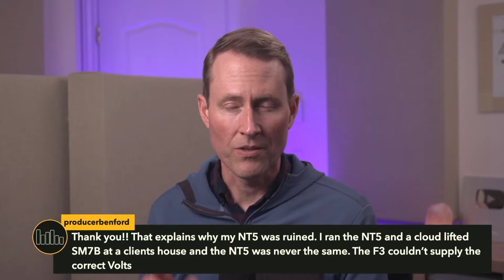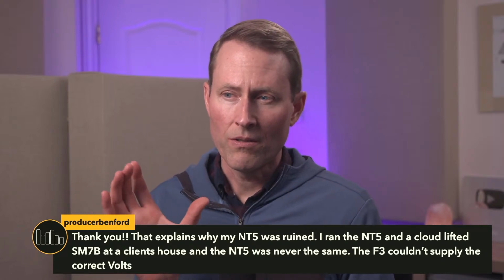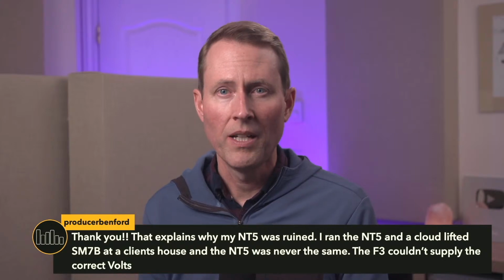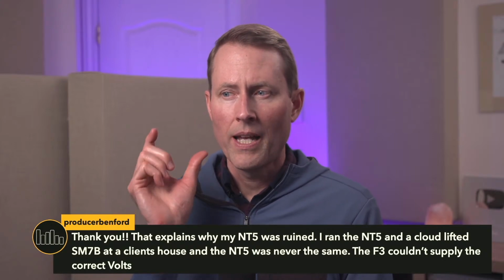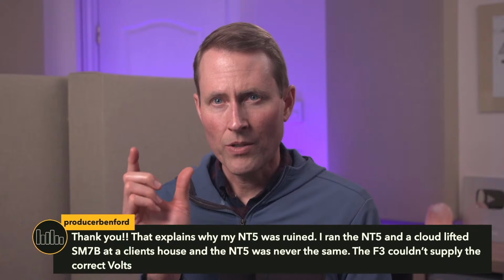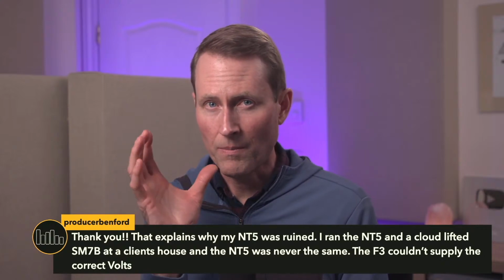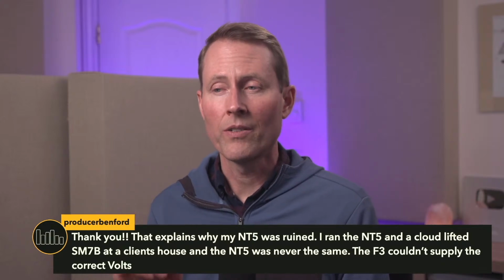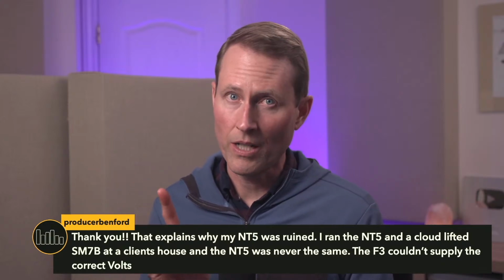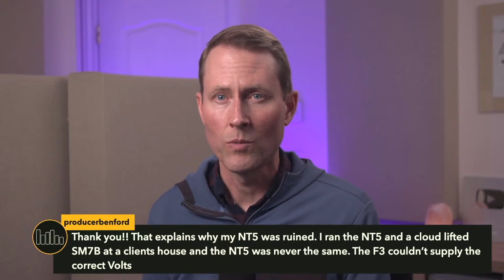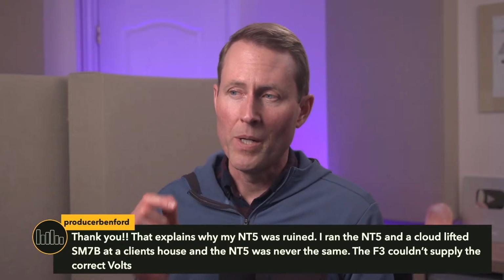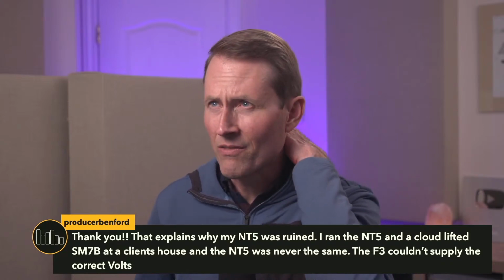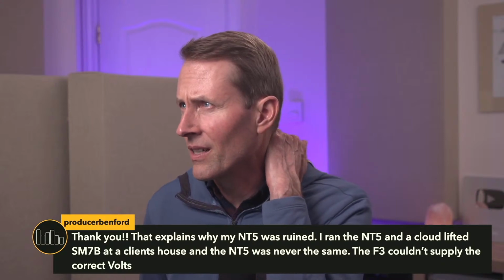And that's one of the limitations. Zoom has a tendency to do things like that, and again, not a bashing session. I have Zoom products. I love them. The F3 is one example where, in an effort to make it more power efficient and to keep the body really, really small, they figured, is my assumption, that most microphones don't require more than 5 milliamps. But in cases where they do, that's where you could run into this problem. And I don't know what the NT5 requires. We can take a look at that, in fact.